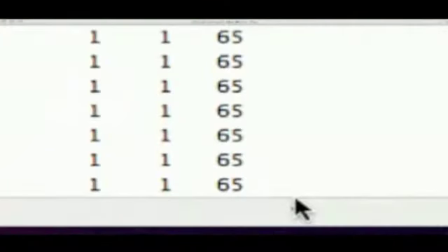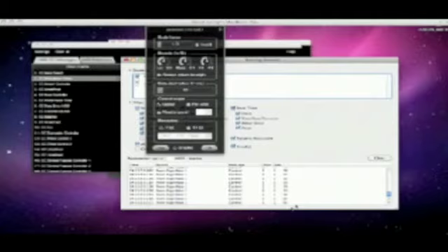So quickly look at the MIDI monitor. If I touch the strip controller, you can see when I first touch it, it's hanging around at about, well, 65, because I had it at 61%, 65. So that's when I first touched the strip controller, and then I can move up from there, or now I can move down from there. Before I couldn't move down because the base was 0. Obviously, MIDI can't go below 0. So now I've got 2 directions of movement. I've got the positive movement if I put my finger on the strip controller and move upwards. I've got the negative movement if I put my finger on the strip controller and move downwards. Okay, so that's the base so far. That's simple enough at the moment. So the base is a percentage of the full possible value, which at the moment is 127 steps.